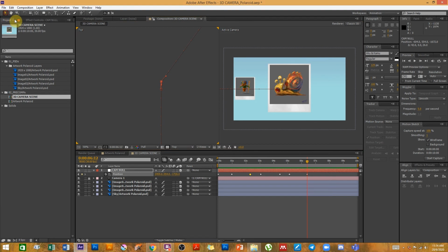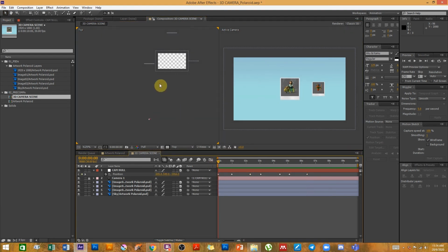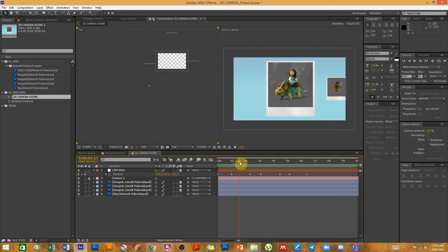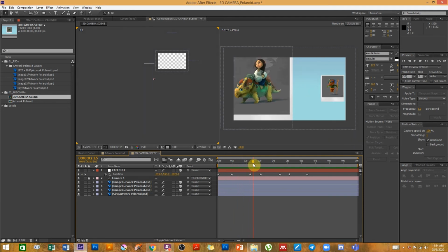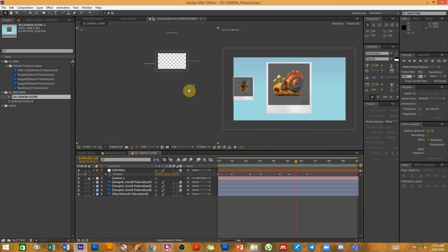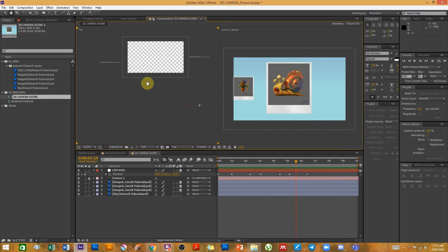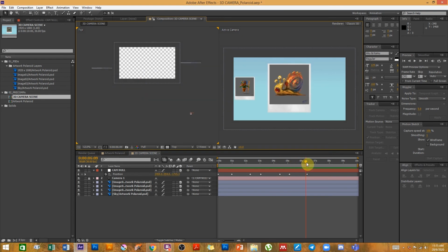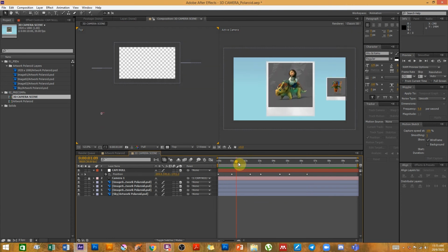And we're done. Okay, so we've moved the camera into 3 different locations and stopping at each location for about 1.5 seconds. So it zooms in, you look at here, and stays here for a while, then it moves off, stays here for a while, and then moves off again. Okay, so it's very simple. Keep your animation clean first, do the foundation movement first. That's what you want before you add in all those angles and stuff. Okay, so now is where we actually get a little fancy.